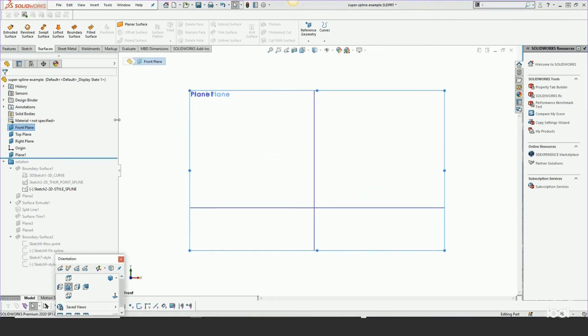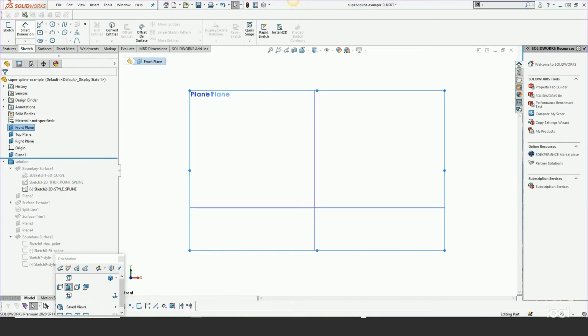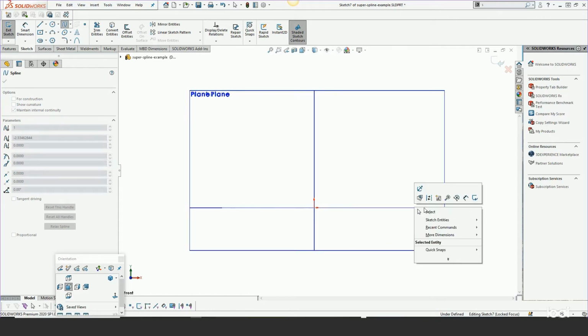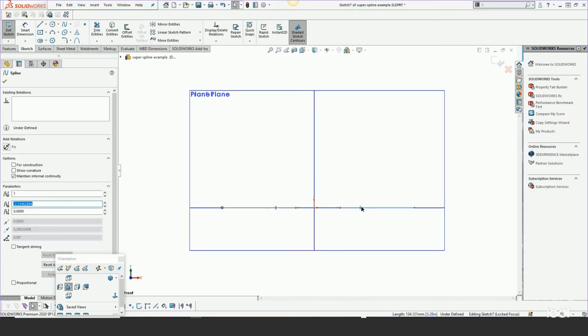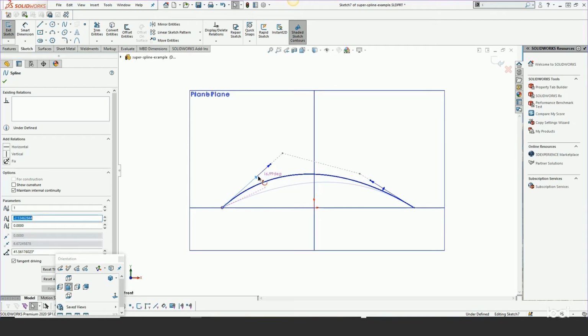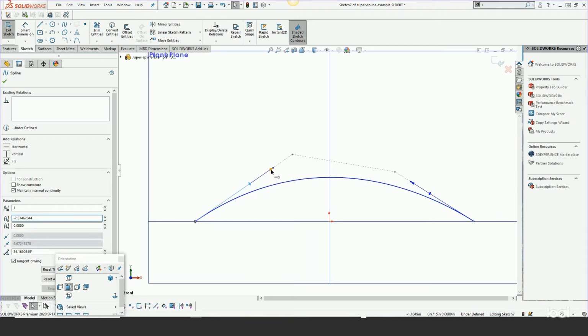So we're going to start on the front plane and start to introduce you to the most basic types, which is a through-point spline. So here I've just done a 2-point through-point spline, and it looks like a line. It's really not. If you click it, you can drag up the angle controls. These are the magnitude controls, which control the amount of magnitude from the vertices. And I generally will not create anything more than a 2-point spline. If it's 3 points or better, I'll probably create a style spline.